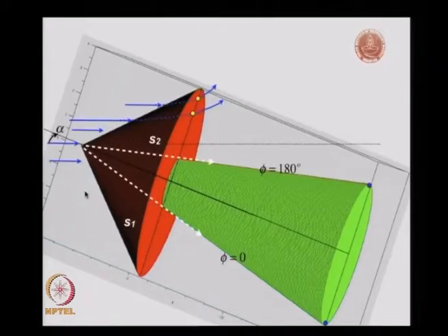Even then the flow will actually move past the mountain onto the other side. That's exactly what is going to happen here. So you have this cone, the flow comes in, enters through the shock, reaches the bottom of the cone surface, and then curls around and goes up to the top.